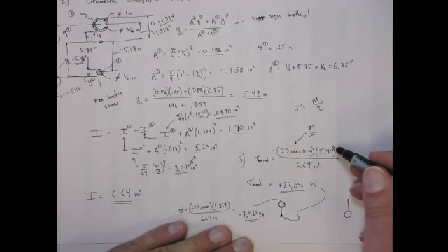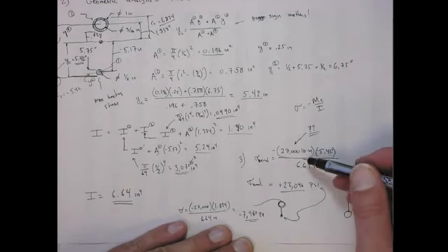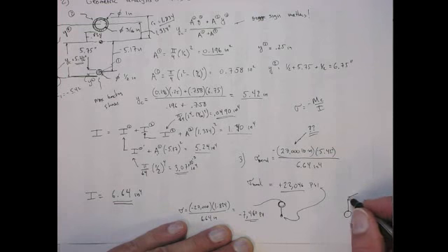The C's would be the same, other than the sign would change. The M would be the same, the I would be the same. But what you would find is you would get the max stress up here, and it would be minus 22,046 in compression. Down here, it would still be in tension, but it would be the lower stress of 7,460. Okay?